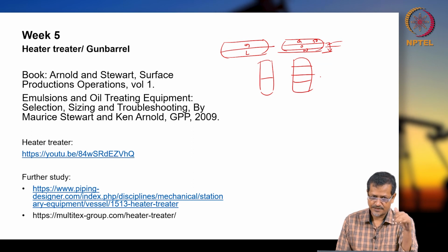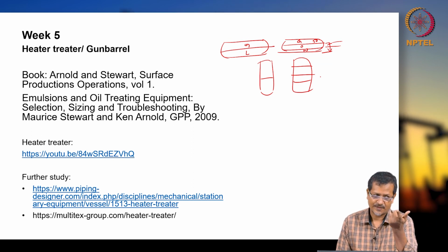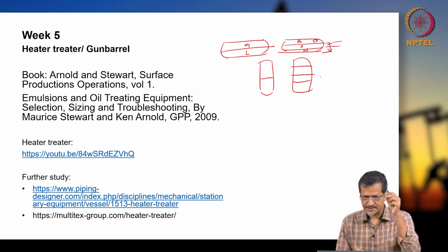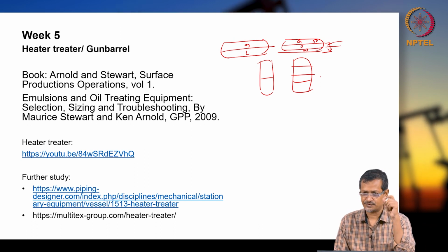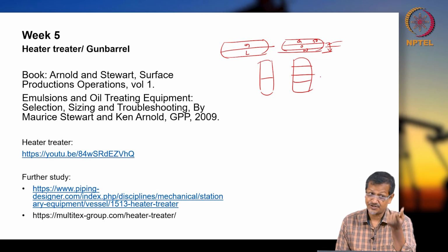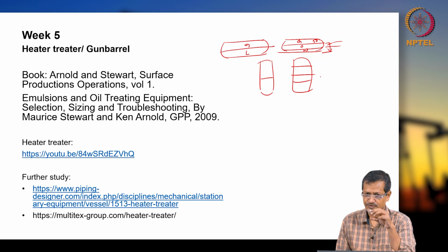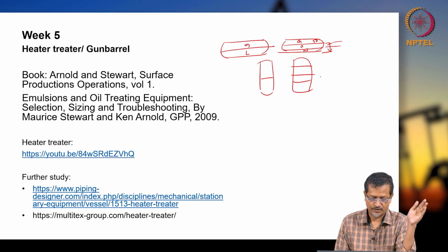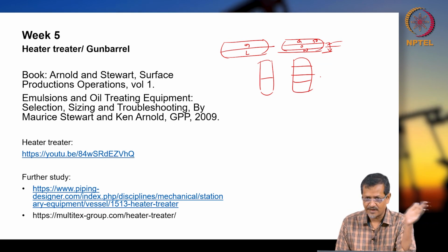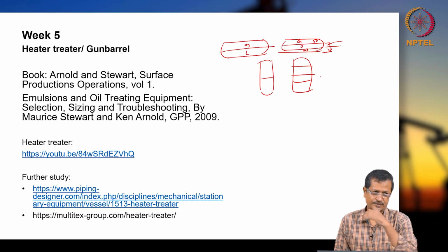You are heating the oil-gas mixture, increasing temperature, and that will change the viscosity. When viscosity changes, heavier particles will settle quickly and lighter particles will move up. So the separation rate will be quicker and retention time will be lower. Finally you are trying to reduce retention time, so your system will be more compact and your process faster, with more fluid flowing through the separator system.